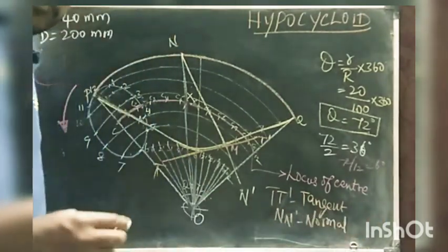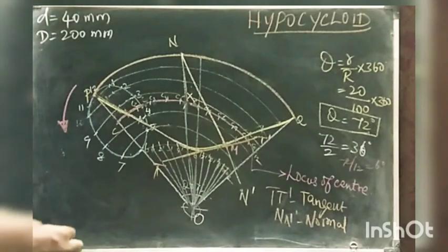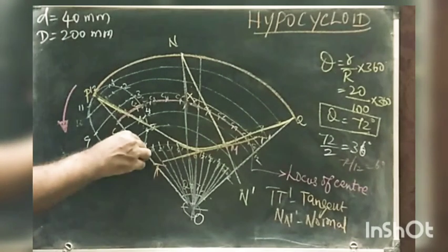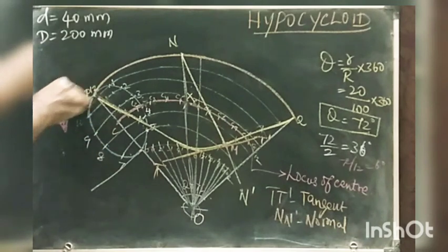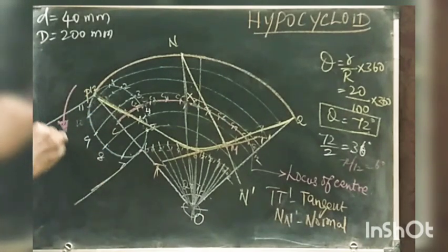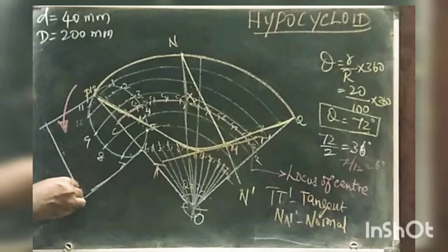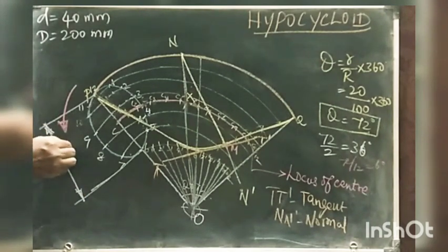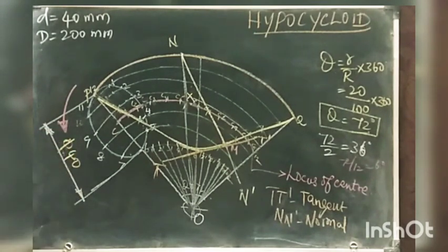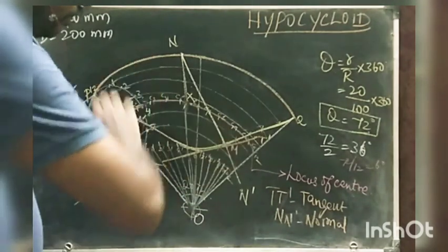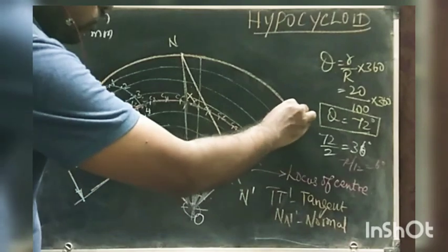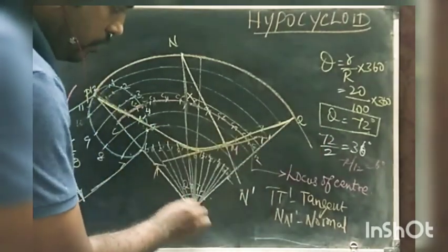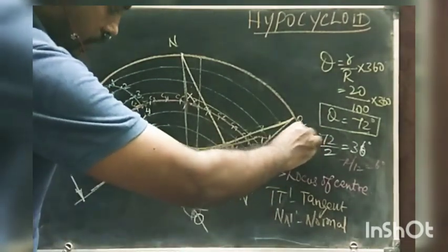And similarly mark the dimensions. That's very important. Just see it here. The circular dimensions are very important. Extend the lines and give the values. It's dia 40, right? Dia 40. And similarly the base circle dimension. What is the base circle? It's from here to here, PQ, right? So the topmost, from here to here. Just extend this line.